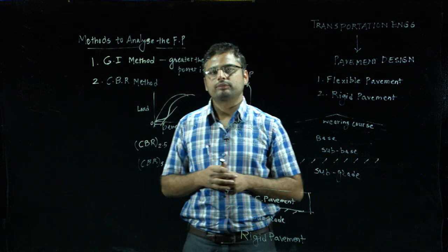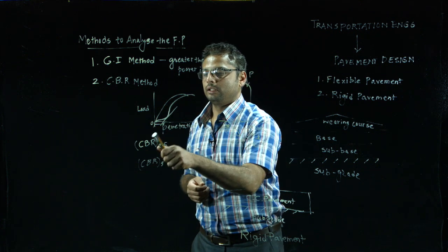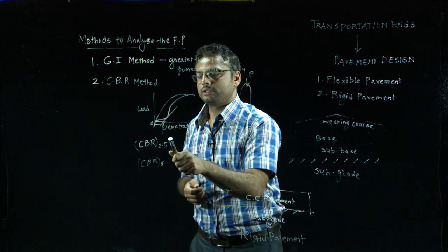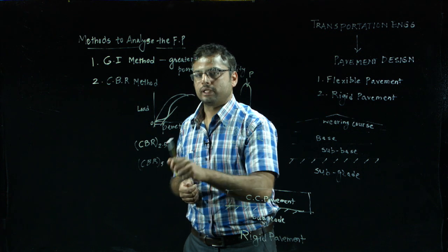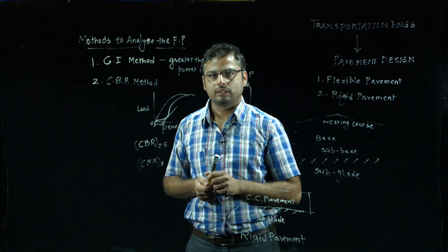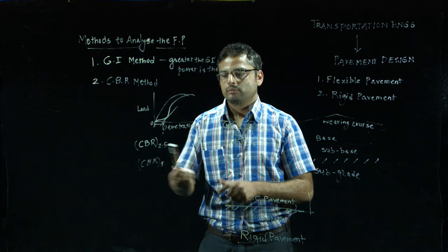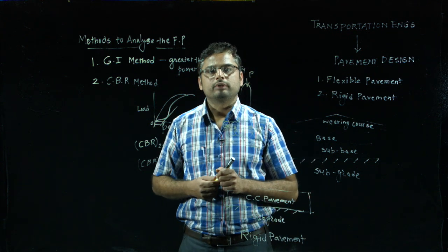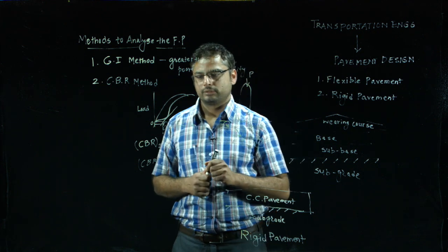So if our curve needs a correction like this, we will have to add this correction to our subsequent load and penetration values, and then calculate the CBR at 2.5 mm and 5 mm respectively. Out of these two values, we have to consider the CBR value obtained at 2.5 mm penetration. If the 2.5 mm penetration value is less, then we will have to repeat the test.